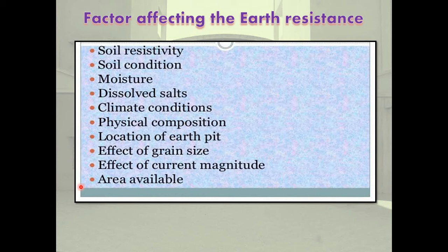It depends on the physical compositions of the soil, moisture content, dissolved salts, grain size and its distribution, seasonal variations, and current magnitude.